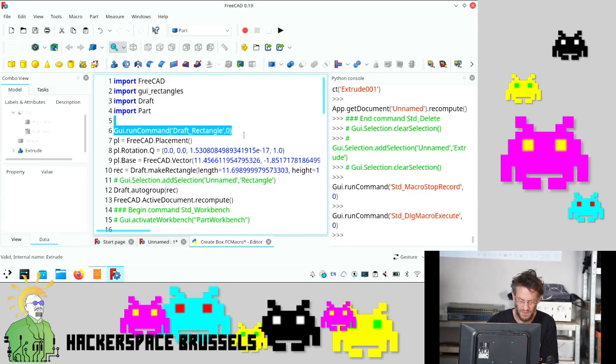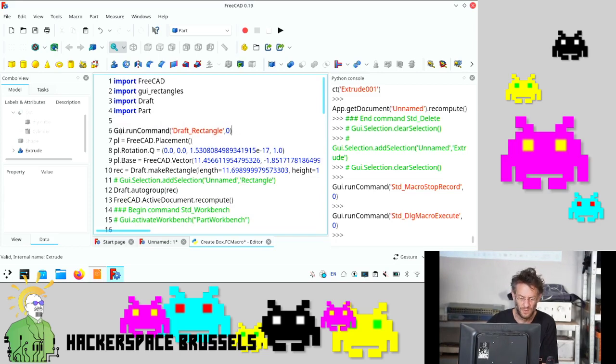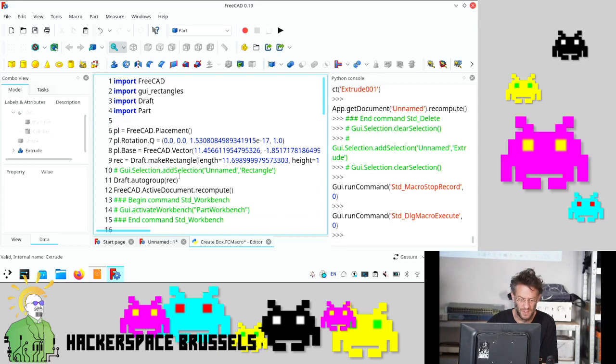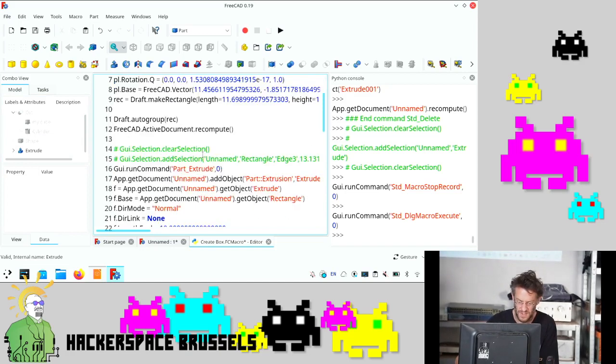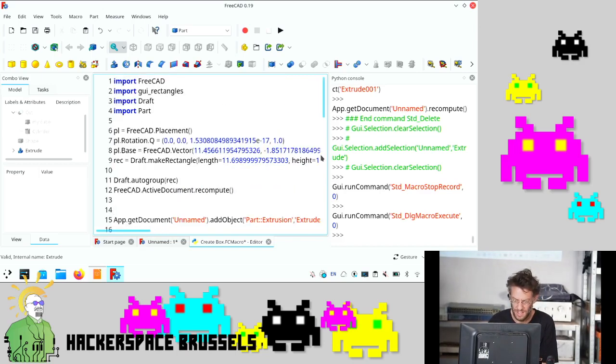we could simplify this a lot. All these GUI commands, we don't need them. Actually, there is a setting in macro recording to not record the GUI commands. That's what I usually add, because you see that if I remove those things, it begins to get really clearer.